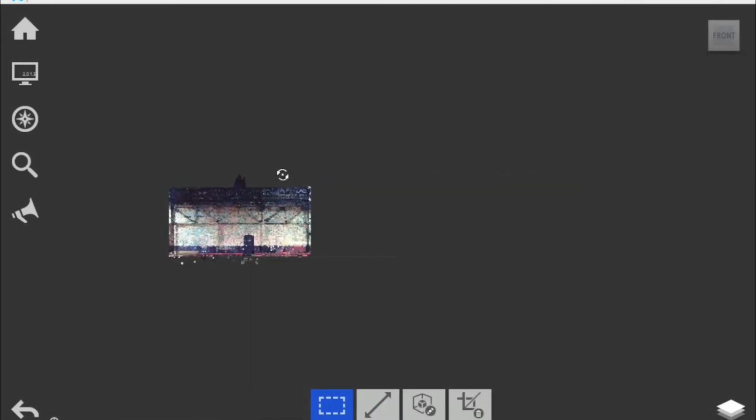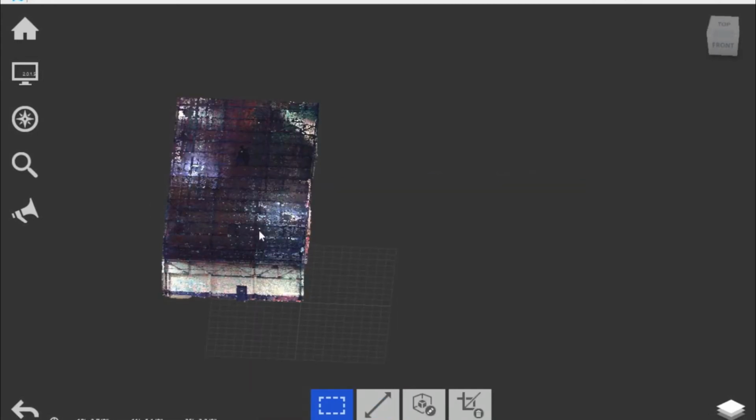You could also use a limit box to do this as well. Really, that's personal means and methods. I prefer using clip regions. Others prefer using limit boxes. So you can go ahead and clip everything outside of that, and then just do your planar view from there. But I'm going to do an unclip all for the sake of time, and just do a plane.